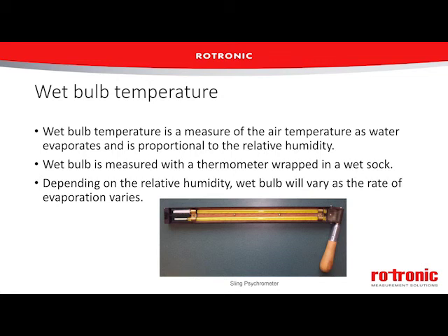And the psychrometer fundamentally has two temperature sensors on it. One to measure what's called dry bulb, which is just the ambient temperature. And then the other one is for the wet bulb temperature. In this case, it's this top thermometer here with the white sock on the end of it. How these work is that sock is wet. There's pure water on it. And then the air is passed over these two sensors. In this case, the sling psychrometer is swung around to promote that airflow.